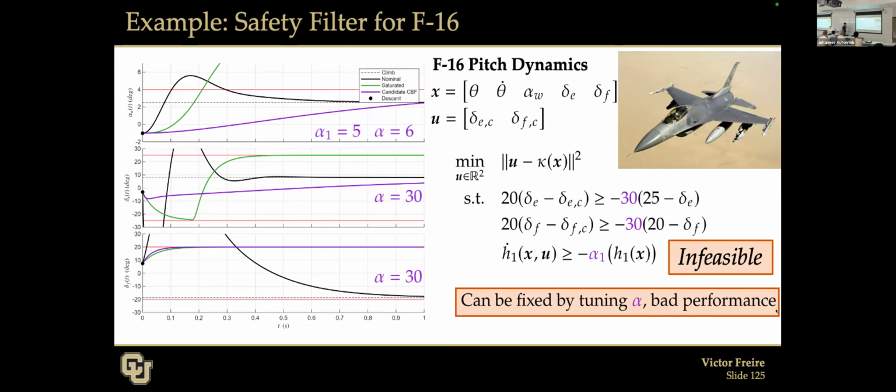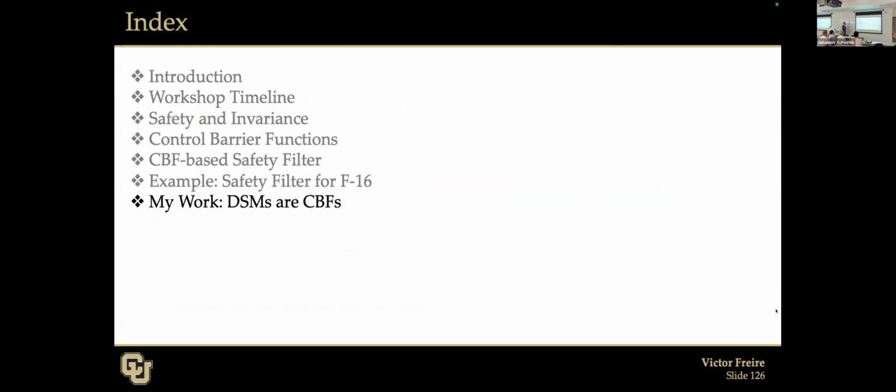What's important is that you have no guarantees that if you go back to the cruise, these new alphas will work there. You have no guarantees that even though you've tuned them now, you're essentially tuning for whatever your starting condition is. So if that changes, you might have to retune, okay? That's the drawback of designing CBFs naively like we just did. Regardless, it still happens a lot, and it's going to give great performance in many, many examples, and you're going to see CBFs do amazing things, even if you're designing them naively like this. So how can we do that? Design the CBFs not so naively.